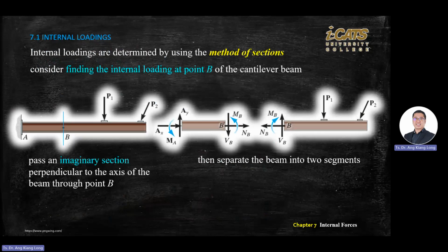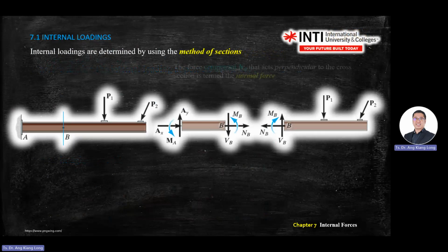Okay, now this VB becomes clockwise because you must cancel the moment on the other side. So basically, actually there's nothing there. You just create some forces to do your analysis. Yeah, so the principle is quite simple. We do not touch the external force here. We just do how we do the cutting. Okay, so far okay? All right, so next, the rest I already explained, what is NB.